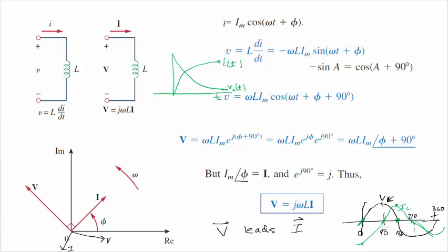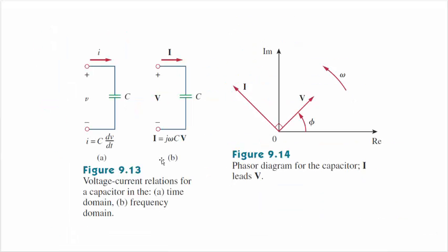So we have a similar thing happening with a capacitor now, and we can go through a derivation as well. Here we have I equals C dV/dt. So this is how C behaves, in sort of an analogy to Ohm's law. I and voltage are related by the rate of change of voltage in a capacitor. And when we go through the math, we'll see the frequency domain relationship for how I and V are related. And again, we have a phase shift term here.